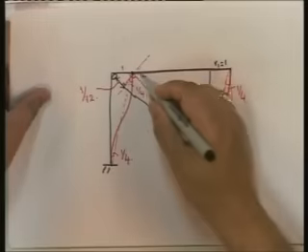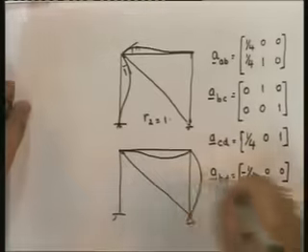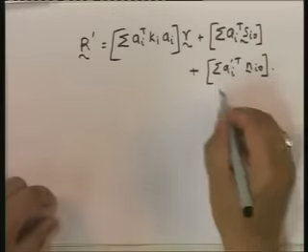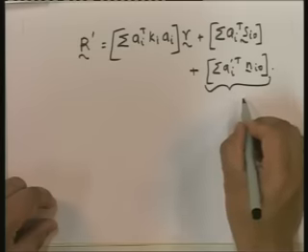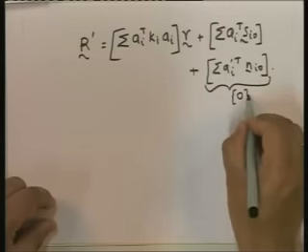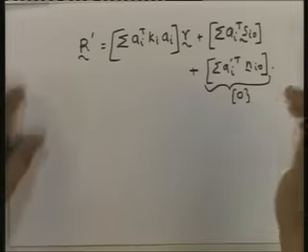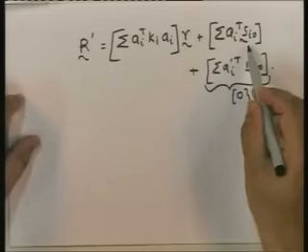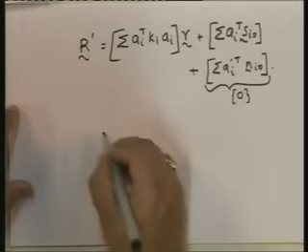Okay? And the major thing is that the Ni 0 are the reactions, and if we look back at the shape, corresponding to this, there is no vertical displacement of these points, and in R2 and R3 there are no vertical displacements. So in this particular case this is going to show up as a 0 vector. This will only show up for BC. So let us do this first for BC.